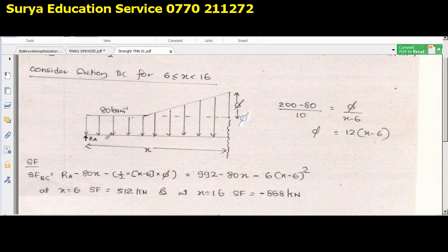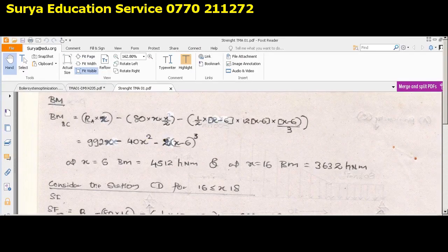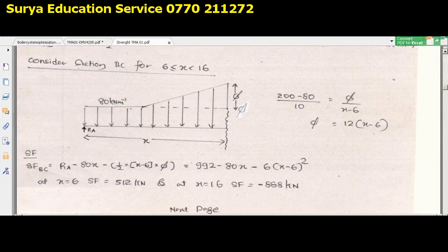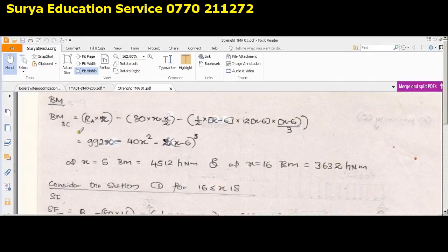The bending moment due to this Ra is positive, right? Acting upwards, so no doubt. Now see, guys, because of this reaction, you can similarly derive it from the previous step. That is a way of checking actually. This Ra tends the left side to move upwards, so definitely it is Ra into this length. What is this length? X, right? Ra into X. I think that part is okay. And 80x times x by 2. Let's see how that comes.